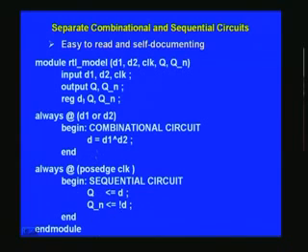Coming back to this, we have not said what a reg is. You notice that the outputs in this always block are d, q, and q underscore n. So these are all registered values. That means it's basically a flip-flop here. It is not really a flip-flop in the usual sense of a sequential circuit, but still it memorizes that event, because whenever there is a change, only then we take action. So some sort of storing is taking place there.